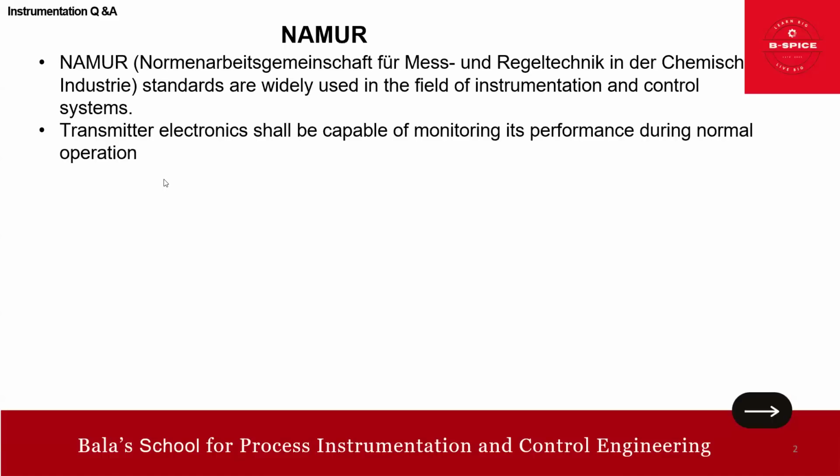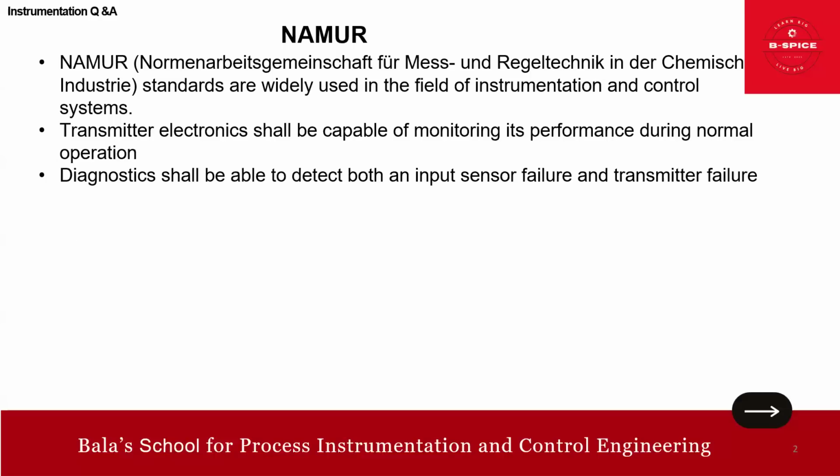Basically, here is what we are achieving. Transmitter electronics shall be capable of monitoring its performance during normal operation. So diagnostics shall be able to detect both the input sensor failure and the transmitter failure.